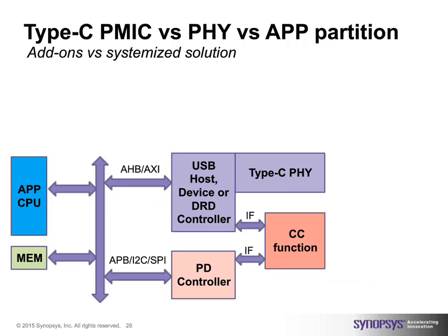They're separate. If we go back to the first USB spec, that was low speed, full speed. And then high speed USB was multiplexed onto the same pin and connector. Then came the USB car kit, the USB analog headsets, USB on the go, and USB battery charging. And all used the same connector and the same pins, and the USB PHY had to include everything.